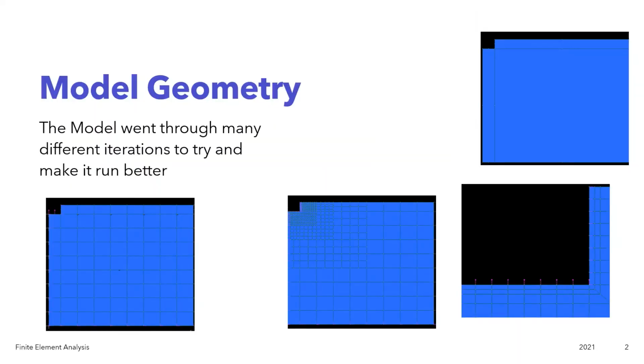We ended up going through about 4 models all up. The first took quite a while to run, so we redid that model, fixing up the gradients. Once we tried to run it to get results, we realized that it wasn't converging. So we went back to the first option, and that model also wasn't converging. So we made a model with as simple geometry as we could, and that model was also not converging.